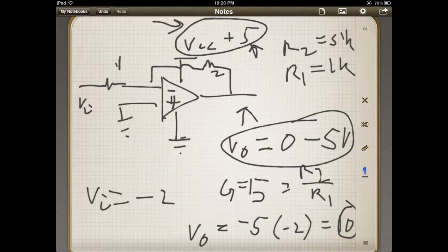We actually rail the amplifier, is what they call it. Okay? So remember that you've got to work within the bounds of what kind of voltage you apply. And depending on what kind of amplifier you choose, some have the ability to go up to 12 volts, or some even go to 30 volts. It just depends. You've got to choose the op amp for your application. Okay.